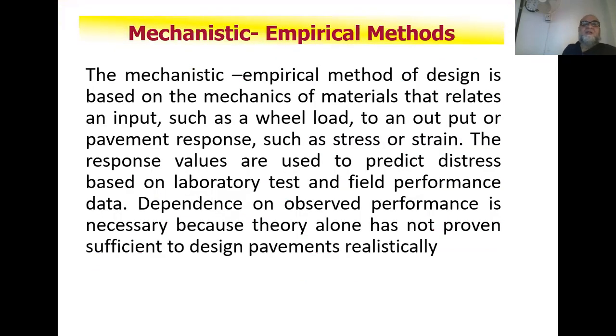The mechanistic empirical method of design is based on the mechanics of the materials that relates an input, such as wheel load, to an output, such as stress and strain. Response values are used to predict distress based on laboratory tests and field performance. Dependence on observed performance is necessary because theory alone has not proven sufficient to design pavement successfully.